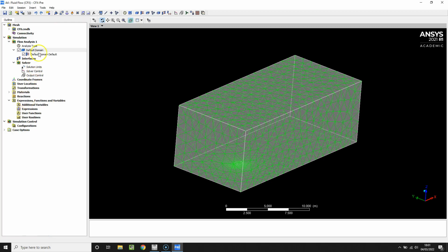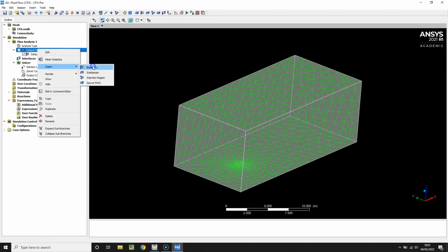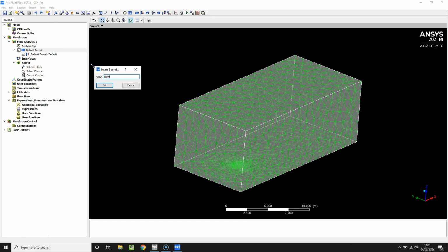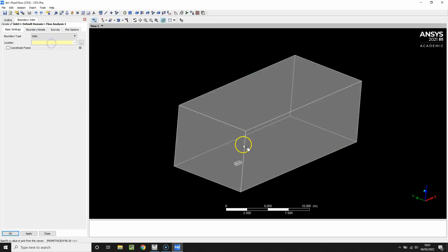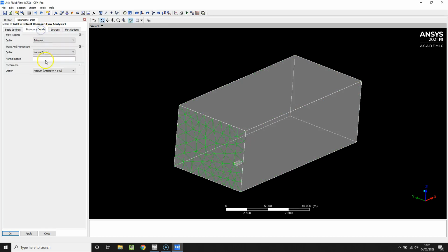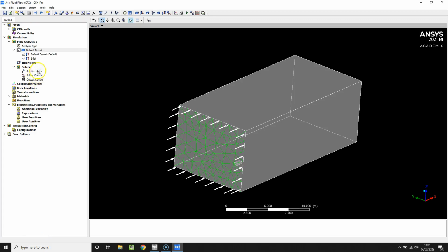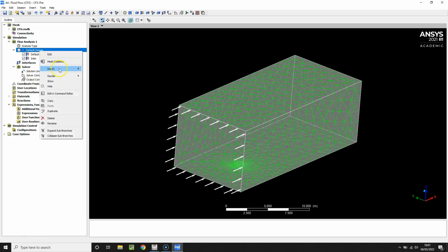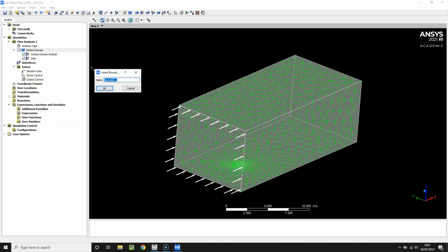And closing. So go for the usual process, right click and boundary. So creating our inlet, put it there, and a speed of 30 meters per second, just dropping the inflow turbulence intensity down. Create the sides as free slip walls.